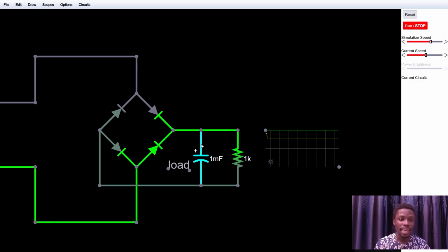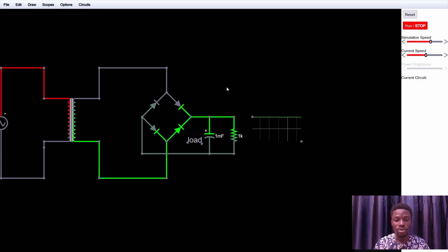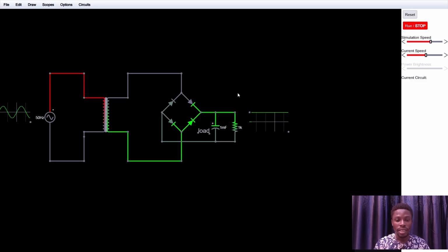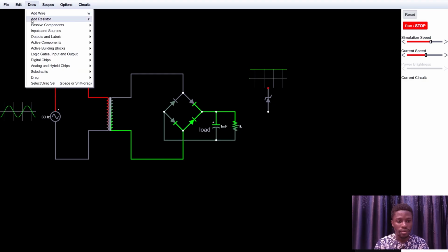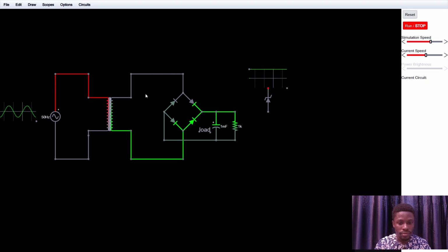Okay, finally, since we are already talking about power circuits, let's add regulation. I mentioned the Zener diode the other time, right? So let's bring a Zener diode into this circuit. So this is a Zener diode. It has to be in the reverse direction. I will move this away, and bring the Zener diode in.